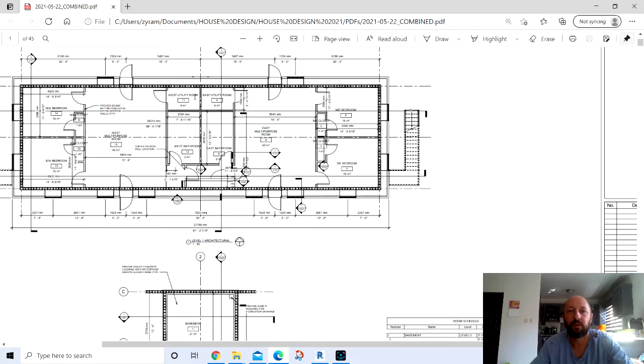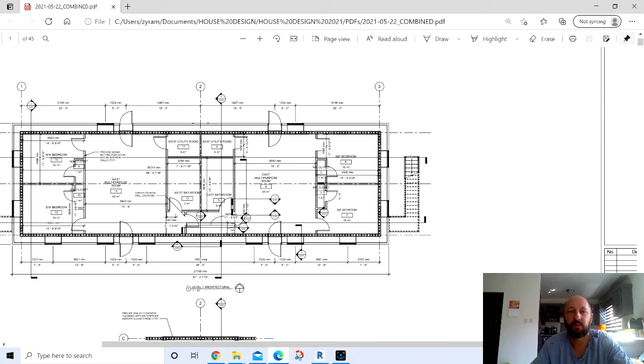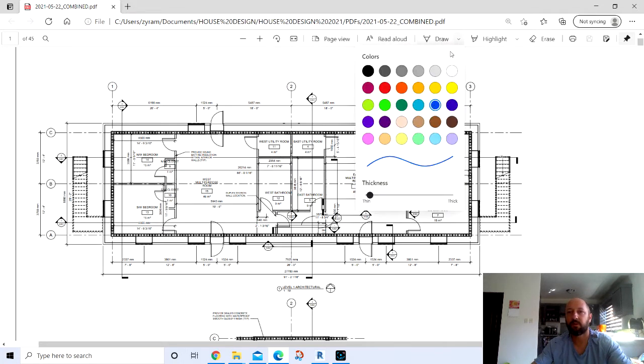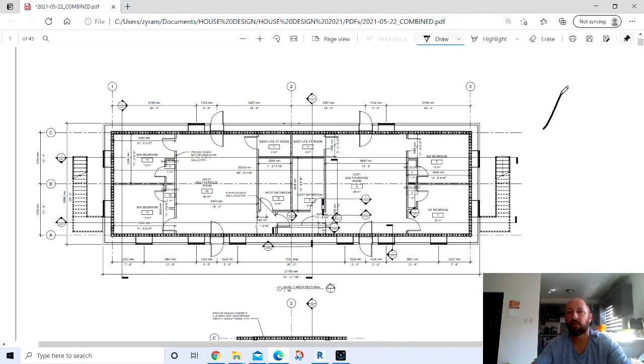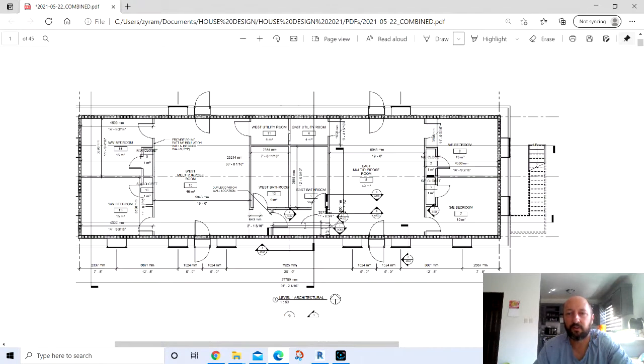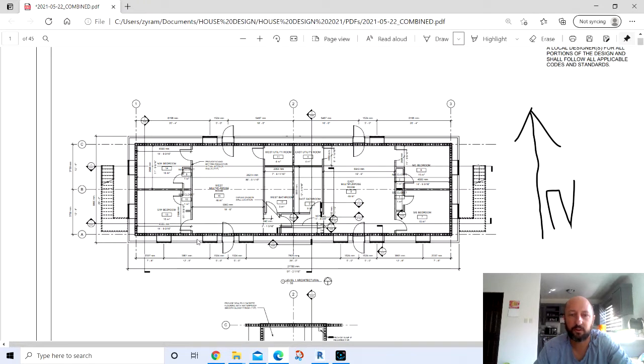So one of the critical things, of course, with this design is the orientation of the building. So you want to have north as page up. So you definitely want to keep north that direction. So that's the basic concept. That's called a passive solar design, to where you have more windows on the south face than on any other face.